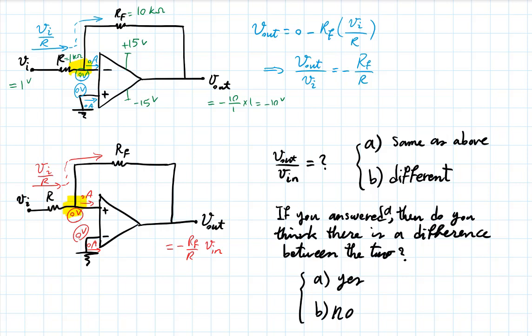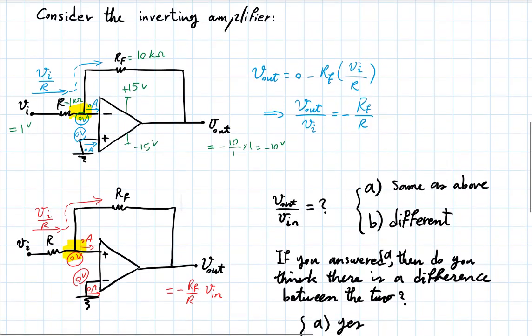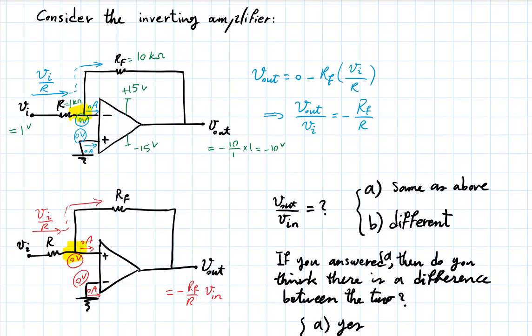And so on, and so on. And before you know it, the op-amp output is stuck at saturation. And if you happen to have a small negative noise induced on this at some point, the op-amp will go the other way. So this is the notion of feedback, negative feedback versus positive feedback.